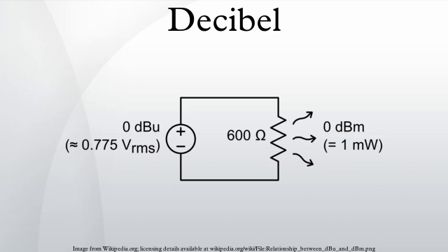Compare dBc, used in telecommunications. Decibel HL or decibel hearing level is used in audiograms as a measure of hearing loss. The reference level varies with frequency according to a minimum audibility curve as defined in ANSI and other standards, such that the resulting audiogram shows deviation from what is regarded as normal hearing. Decibel Q is sometimes used to denote weighted noise level, commonly using the ITU 468 noise weighting.